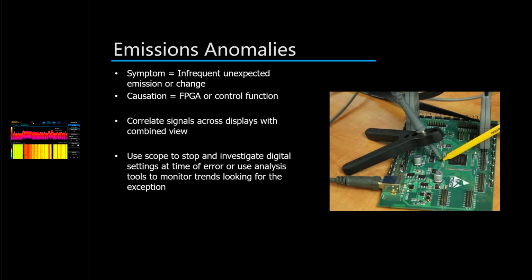And so here we were predominantly using the... we did some triggering on the scope, but we weren't really triggering in a combined way. This was more of a visual correlation, right? The slow timing of the pulse buildup really makes it such that you need to visually see what's happening on your logic and what's happening on your spectrum analyzer as it develops over time. And eventually you can find that problem by really looking in the close area on the board there.